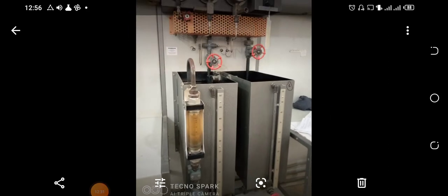So basically this is section 10, the delivery tank. These are the gate valves to open the steam and to open the water from the delivery tank to adjust the flow. In this experiment we set some level of water, and when we open the nozzle, the amount of water sucked from this tank will be delivered from that tank. After some observation we calculate the volume flow rate of the discharge tank.